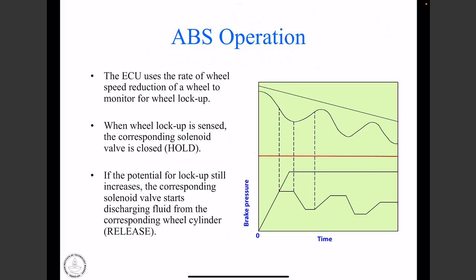Now let's look at an interesting diagram which explains qualitatively how this ABS works and also the reason behind the pulses. In this curve, what we have plotted is the following. This is the longitudinal vehicle speed, and this is the circumferential wheel speed, Vx and V0.